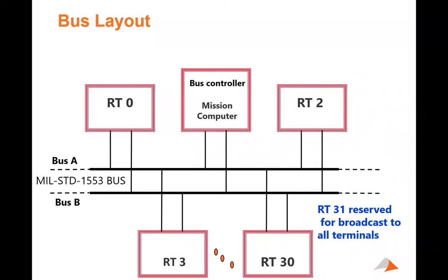Here also that we don't show it here, but you'll see them later on. As the RTs and the bus controller boxes are coming down and connecting into bus A and bus B, this is a coupler. Historically there are two different ways of coupling to this wire, but the method that's used now is what's called transformer coupling, and that keeps the common mode problems out of the way.